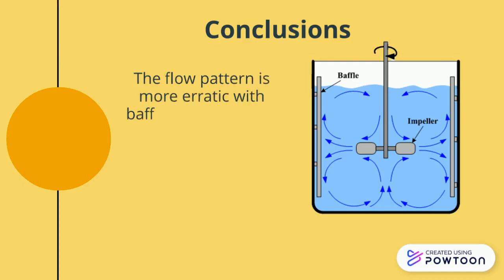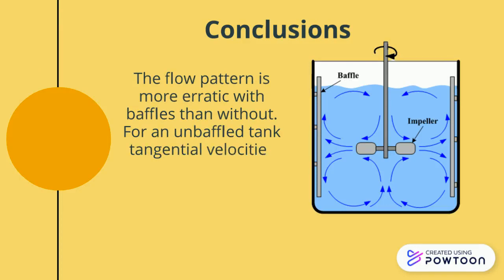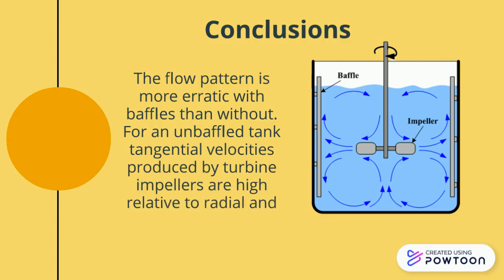The flow pattern is more erratic with baffles than without. For an unbaffled tank, tangential velocities produced by turbine impellers are high relative to radial and axial components.